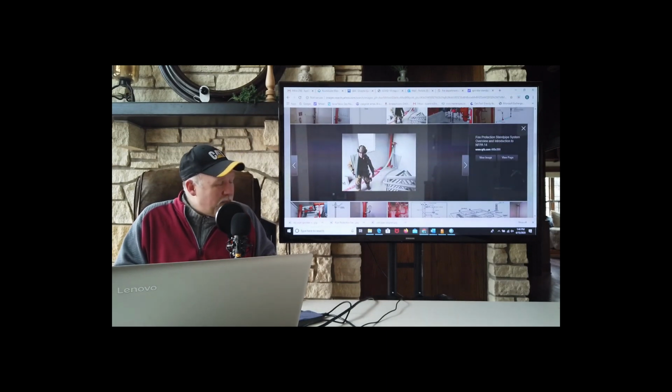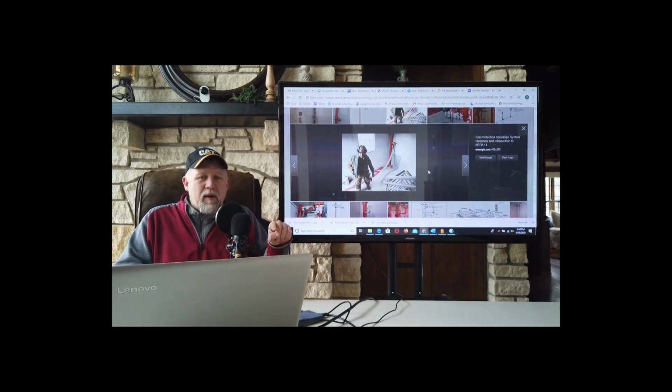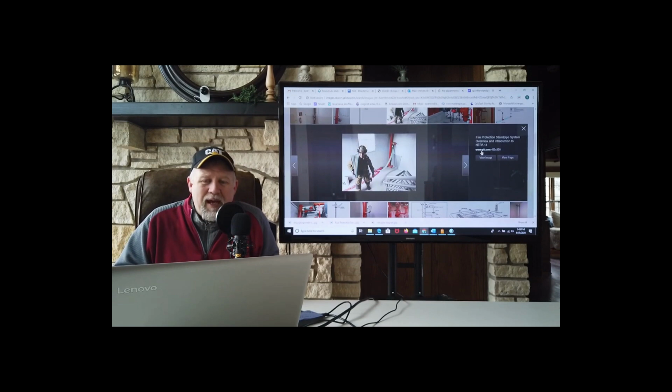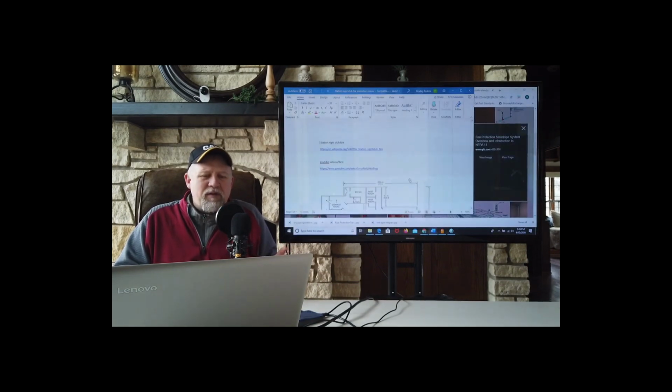Now, you can imagine, by the time the fire department shows up, gets connected, hauls their hose to the appropriate floor, and finds the fire and then starts to fight it, quite a bit of time can pass. So while standpipe systems are code compliant, there are better alternatives, and those alternatives are the automatic sprinkler systems.